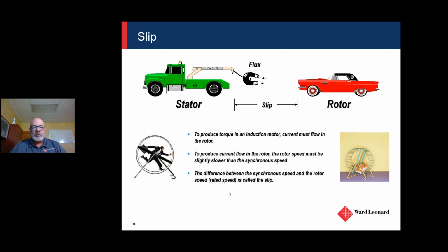So you're going to have an electrical rotation that has a certain frequency and a certain speed, and the rotor follows that, but it's not quite at the same rate. That's why if something's rotating at 1800, we'll see RPM on a nameplate shown at like 1750 on a 4-pole motor, slightly less. Because you have this rotating magnetic field, the rotor is induced, and as the magnet is pulling it around, it follows it, so it's slip, and through that slip you get torque.